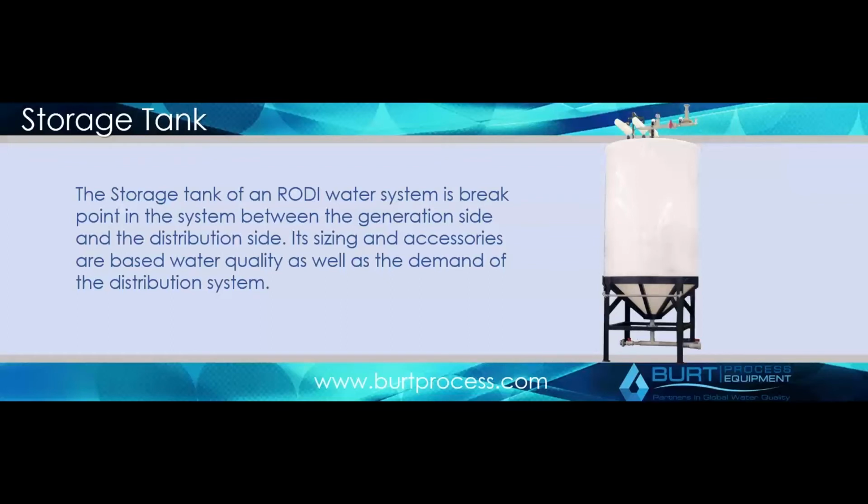The tank is sealed to the air. You have vent filters up here, 0.2 hydrophobic filters to prevent anything from getting drawn into the tank during either the pump down or the vacuum phases of your tank. This is also where your sanitization process typically begins, whether it's chemical sanitization or steam or hot water. Obviously, a plastic tank here, we're talking about chemical. If you're in the pharmaceutical industry, you'd be talking more about stainless steel in those cases.